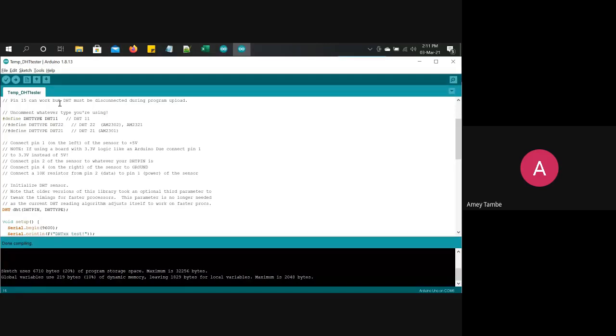So here also we'll have 3 pins. One is plus, second is out, and the other is minus. Plus means the voltage, so it will go to a volt pin. Now this DHT11 works from 3.3 volts to 5 volts. It is already written over here. So it can work on 3.3 volts or 5 volts. But still, you can experiment with it.